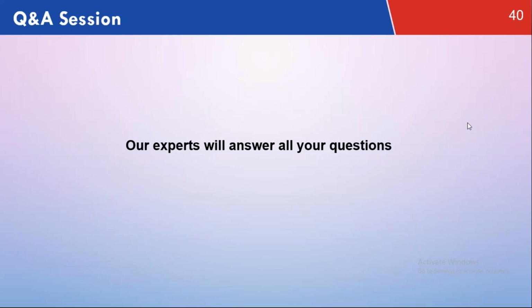That's a good question indeed. I would like to explain. First, we need to know the difference between REACH and RoHS. RoHS is evaluated at the homogeneous material level, whereas REACH is evaluated at the article level or immediate component level. RoHS bans the substances which are present majorly in electrical and electronic products within this directive, whereas REACH applies to all chemical products used. So even though the substance is present in REACH, REACH is for all chemicals, whereas RoHS is mainly for electrical and electronic products.